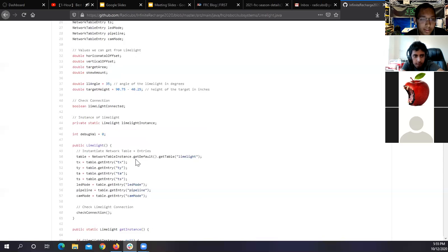So remember that we use the Limelight for vision processing, and we were using it to detect the targets. On the power port, which is the target that we shoot the balls at, there were reflective pieces of tape. The Limelights have really good LEDs, right? So the light bounces off and illuminates them. With the Limelight, we're able to track those, and we were using it so that the robot could automatically align. All we need to do is go near that thing, then the driver number 2 on the button board presses a button, the robot automatically aligns, and you press another button and then it shoots the balls.